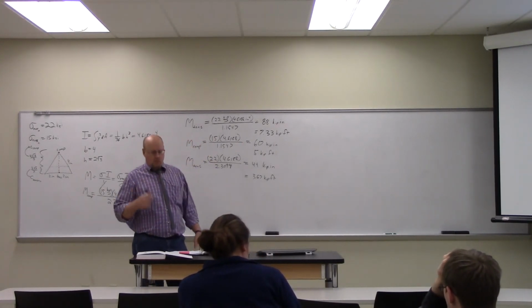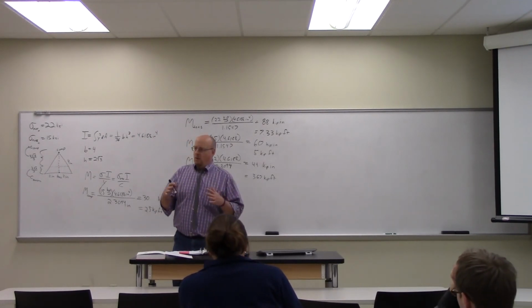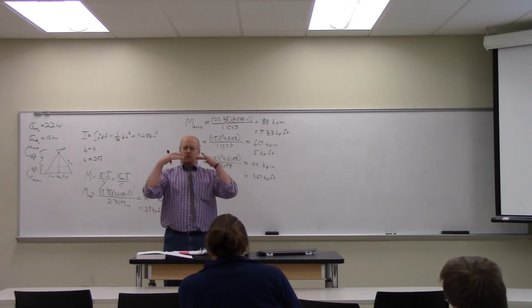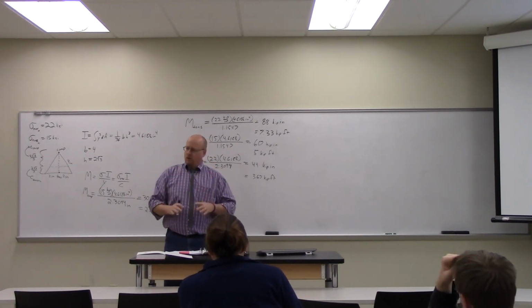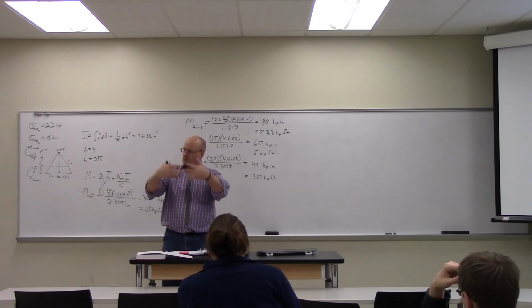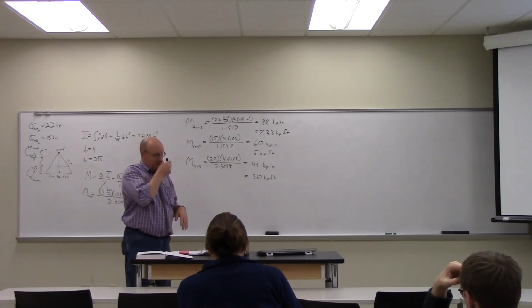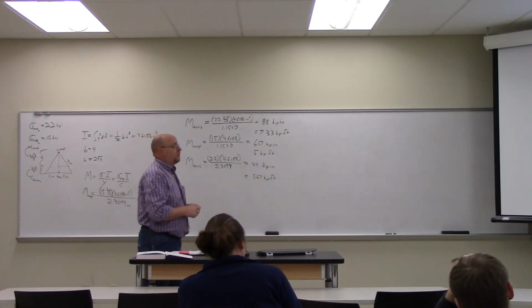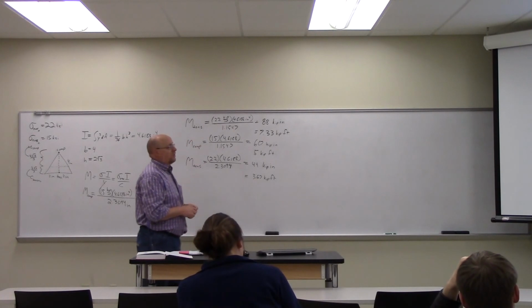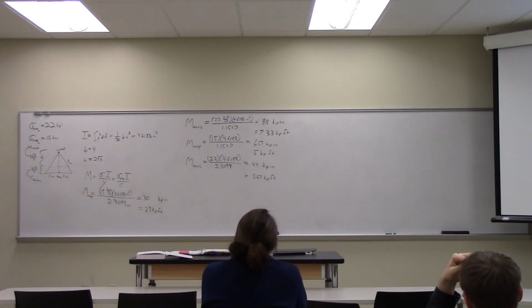Basically, if you look in the book, I haven't drawn anything up here, but there are three-dimensional pictures of a sloped surface, where here the stress is going in, and here the stress is going out, and it's linearly related to y, so that they're flat surfaces coming out. And don't worry about that. But determine the moment that must be applied to the beam in order to create a maximum stress of 80 megapascal. So, what are they asking in the second question, 676?